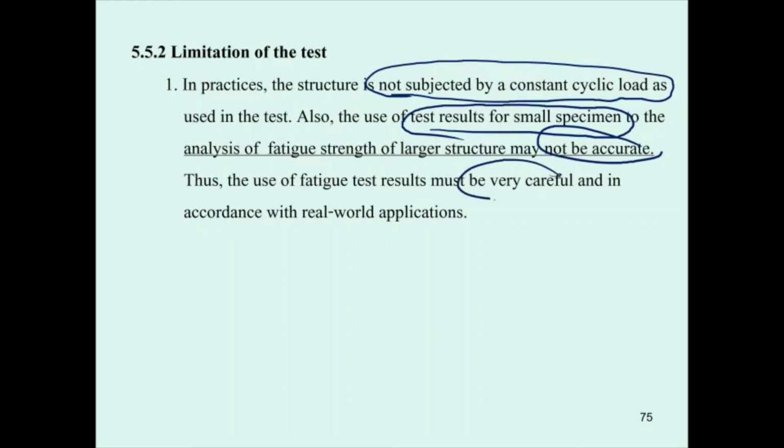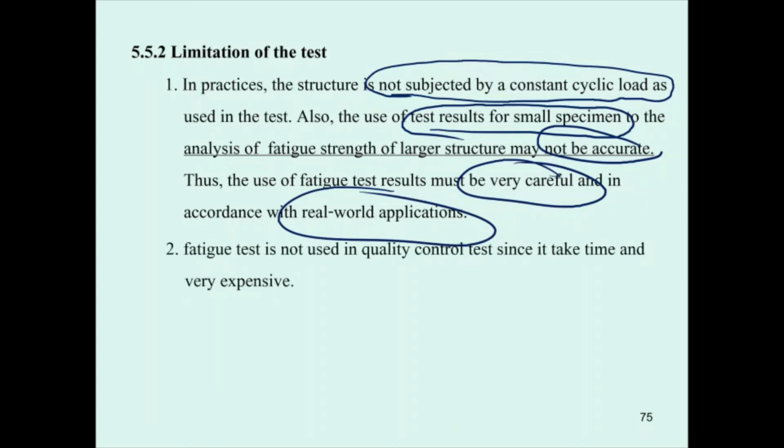Using the result must be done very carefully for real world applications. And second, fatigue is not used in quality control tests. I mean, the steel company usually does not do fatigue tests for the steel. So if we need to do it, you have to do it by yourself.